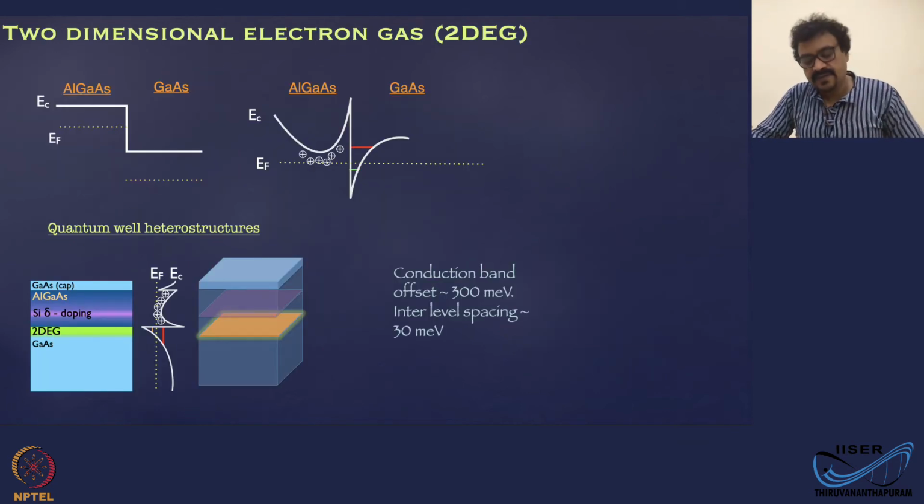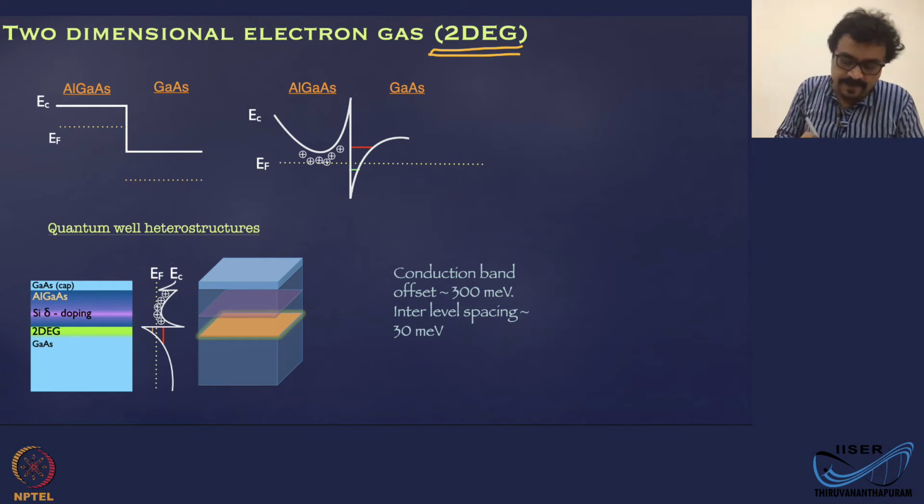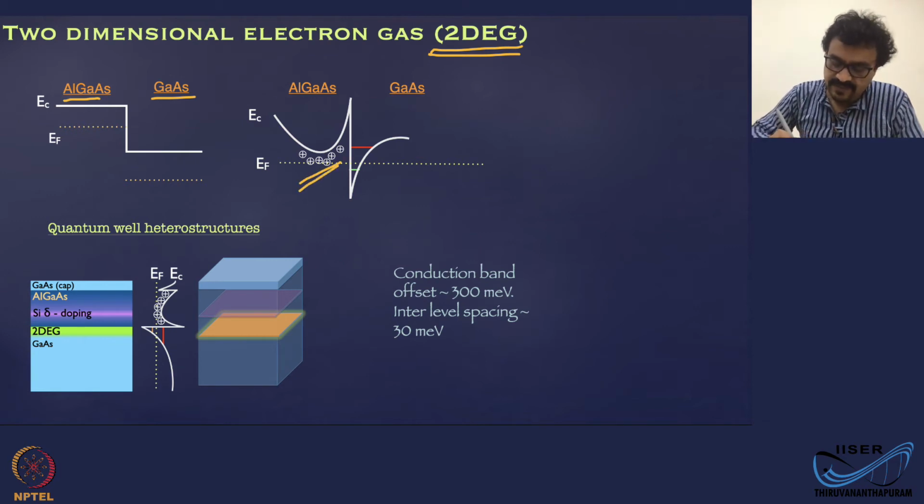Now, I have spelled out the two-dimensional electron gas, or 2DEG in short, in a couple of previous lectures. But let us now define what it is. So this is the type 1 gallium arsenide, aluminum gallium arsenide heterojunction, and this is the quantum well. And we explained in the previous slide that the dopants are sitting somewhere else, and the electrons will end up somewhere else.